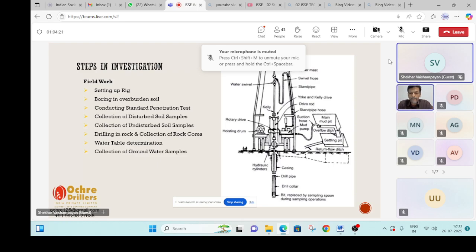And that anticline actually moved during the earthquake. Three-fourths of the bridge was already constructed, and we were not able to get the alignment. The abutment on the front side shifted by 2 meters. So this really did happen. It's good that Mr. Dalmia brought this up. So we had to curve the bridge to meet that situation. The end of the bridge was turned to meet that road.